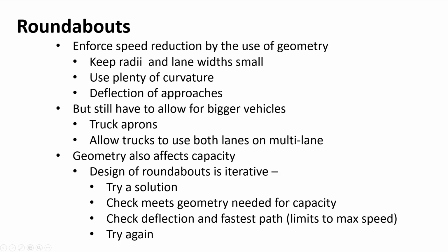We have lots of curvature. There are lots of curves coming into them typically, and we like to deflect those approaches. So you can't just come straight in at high speeds. You're going to have to deflect the vehicle. You're going to have to curve the vehicle a little bit to get around the center island.